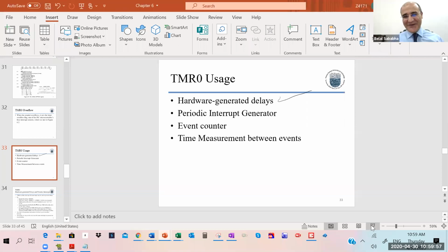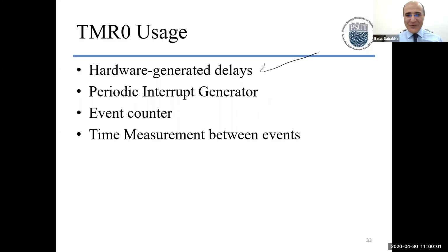Okay, so I'm not gonna do any more things here. Okay, you see how you can do a beautiful periodic interrupt and keep your loop empty. If you can do everything there and keep the loop for other stuff, that would be moving things along, and making the most out of your CPU is the good thing.